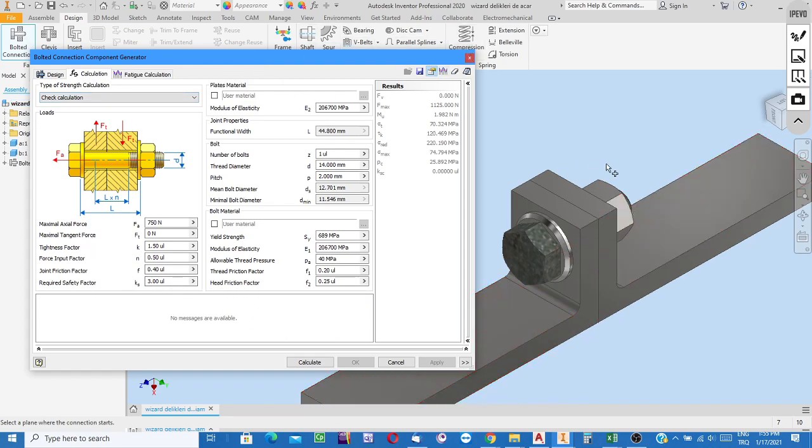Since the existing one is bolt-nut, not a capscrew, here in the schematic figure Inventor knows that it is not a capscrew type connection but a bolt-nut type connection. I have the schematic view of such an assembly. But if it were a capscrew assembly, then I would find a different schematic figure over there.